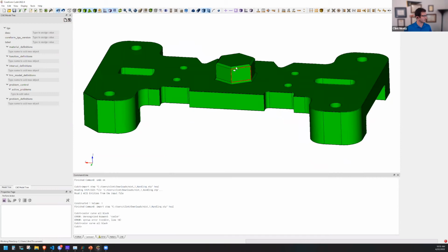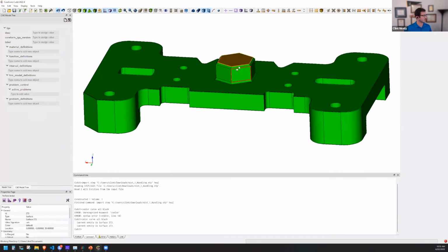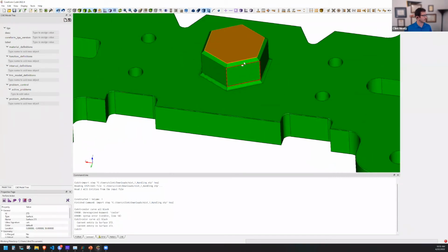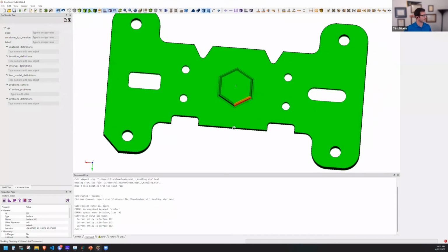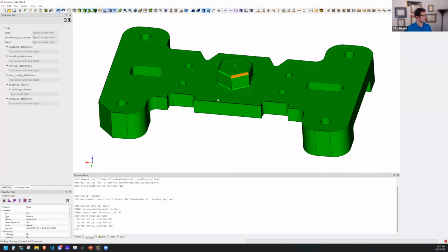And we might also remove these chamfers at the top of it as well. For some areas that we may not be interested in, some of these holes might be filled in as well, to just increase or decrease the mesh complexity. But for our case here, we don't necessarily need to do that. All we would need to do is just surround it in a mesh.